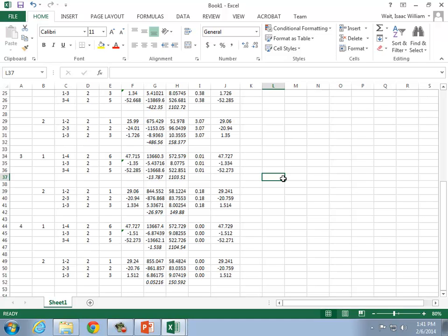Pretty brilliant, right? That's the same process that can be used in structural applications, but here it was used to make sure that regardless of path taken through the network, you have the same amount of energy at every location regardless of path. So at 4, you should be able to go through this pipe or some other path and get the same amount of head at 1. This is an energy balancing method. It's accounting for the energy in the system so that regardless of the path you take from one point to another, you get the same amount of energy at the destination.